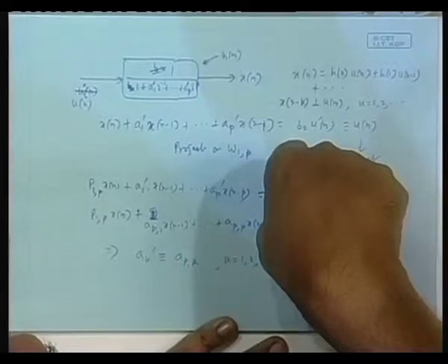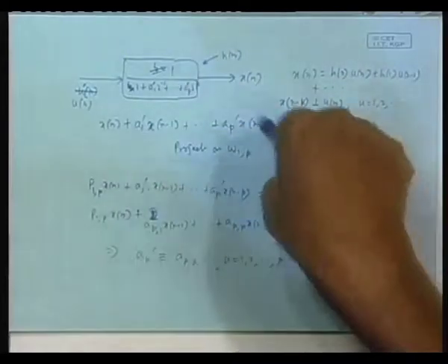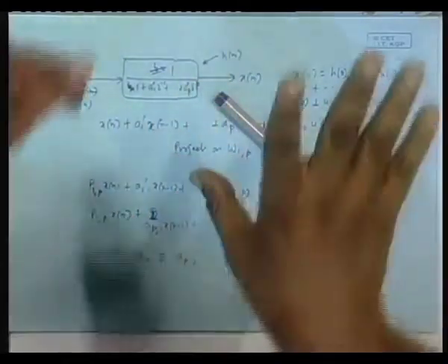Okay. Mind all these things we are doing. This is my approach: do linear prediction, use the orthogonal projection treatment with vector space concepts, get the lattice, forward prediction error, backward prediction, everything, and link AR modeling with this by this theory, and therefore you obtain the AR parameters from just those coefficients. But in the book there is also another approach, for those who are not familiar with vector space theory.